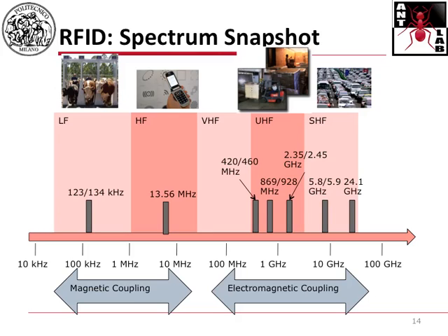So if we are talking about low frequencies or high frequencies, meaning up to tens of megahertz, usually the technique which is used to scavenge energy, so to provide energy to the tags, is called magnetic coupling. Just to anticipate, this means that the tag gets energy out of the magnetic field which is generated by the reader. We'll see in a second what this means.